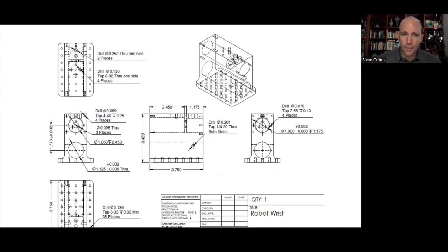Okay, you have some guesses? There are a few good answers in this case. One would be aluminum, because this is kind of a medium component. We sort of imply these medium loads. There's this place where we're going to put a motor in there, but it's sort of connecting everything together. It's at the end of your robot arm. Maybe you don't want it to be too heavy, and it has a lot lower density than steel. That could be a good choice.